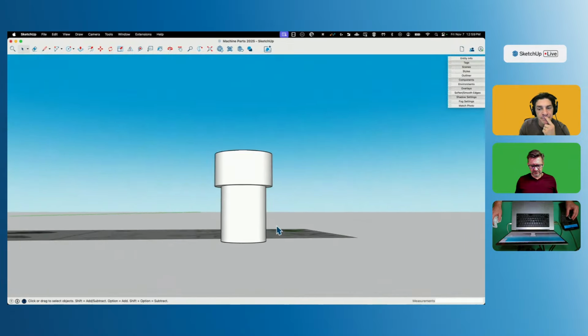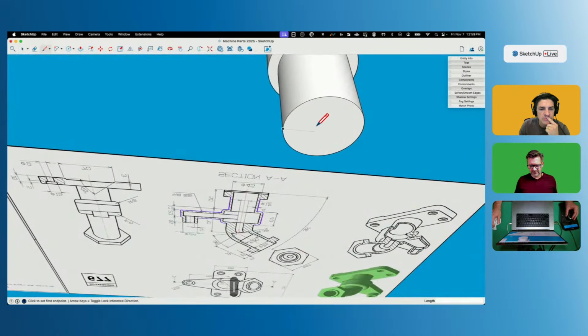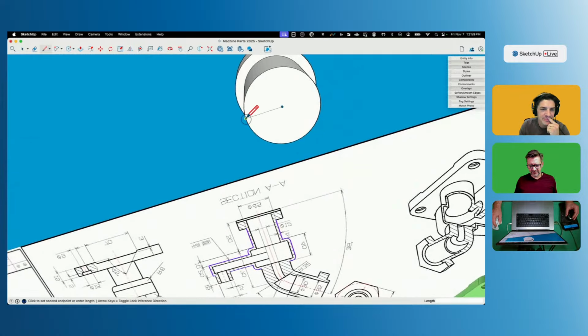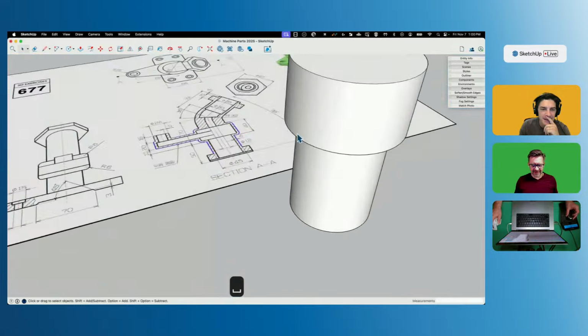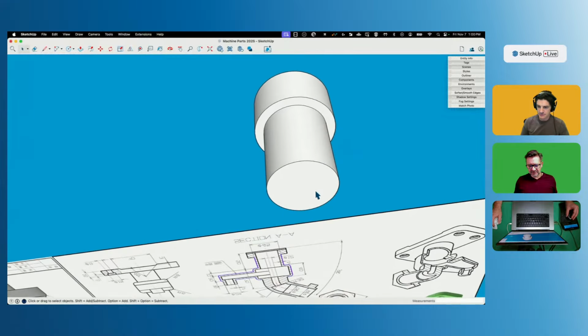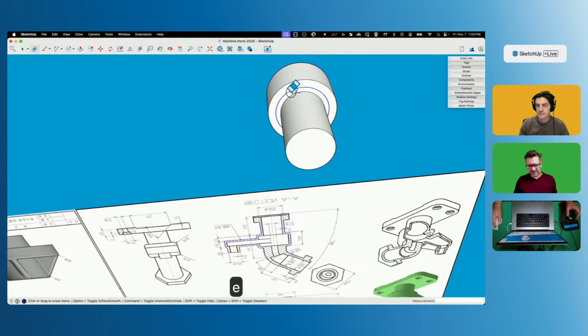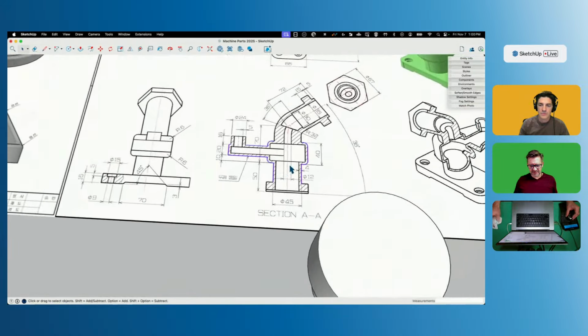What radius did you do for the bottom? I might have done 45. That's when you're doing your 3D mouse spiel. Infomercial. I did not want to interrupt. I did 45. It's not 45. It's 45 minus 8. So that's the problem. This is off, so I'm going to draw a new circle. Actually, I can just take this circle right here and offset it by 4. I'll bring it 4 on either side, and then I can push-pull that up. Oh boy. Clean that up. Connect that back up like that. Get rid of all this. That looks closer. That looks better. Okay, cool.